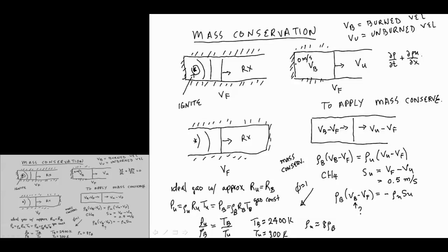All right, and I don't expect you to know this, but I just want to make sure that you're happy with where I'm going next. This says ρu, if I integrate this, is equal to minus the integral of dρ/dt dx. So as I look at the mass flux anywhere, once I know it somewhere, and I know it at the wall, where it's 0, it's equal to minus the integral of dρ/dt dx.